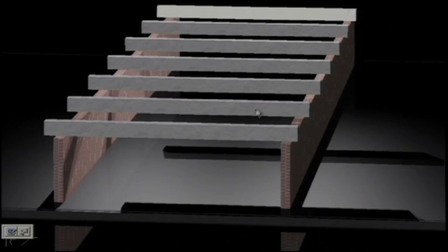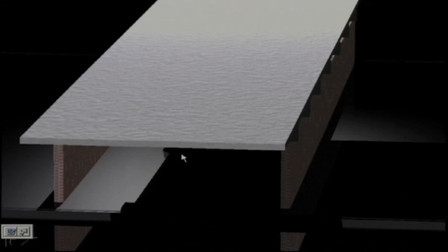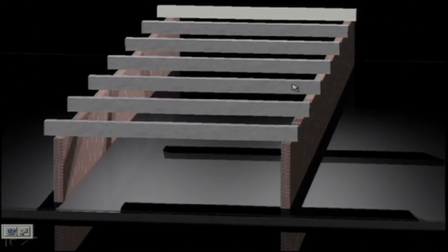we shall not construct in this fashion; this is just to give you an idea of how we are going to do it. In the actual case, with shuttering and other things, everything will be integral, and over that the slab will come. So, we cannot see the beam separately. Our case is that we shall cast the beam as well as the slab integrally, so that we shall get a T section, and we can design it as a T beam.